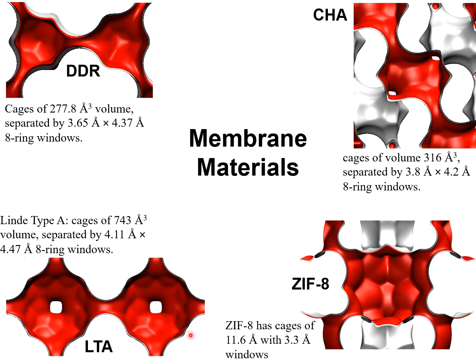A common characteristic of all such materials is that the membrane permeation selectivity is favorable to water pervaporation due to the fact that the diffusion selectivity favors water and the adsorption selectivity also favors water for feed mixtures that contain less than about 5% water. This is not an obvious conclusion, but I'd like to elaborate on that.